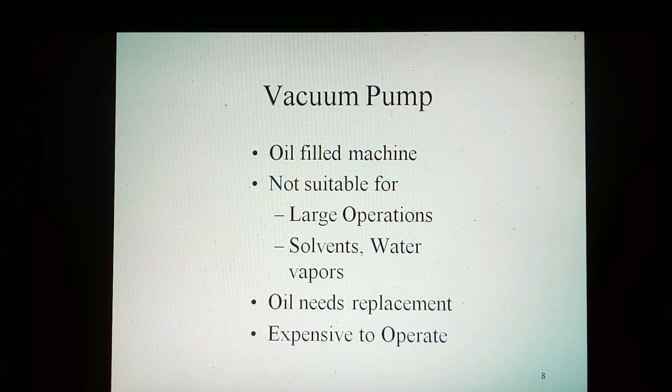Vacuum pump. These are available in single and double stage and are oil-filled, rotary vane-type positive displacement pumps where not only the complete assembly is immersed in oil, but the shaft seal is also designed in such a way that it totally eliminates the possibility of suction of air through it. These are designed to achieve maximum vacuum in a very short time, and the rise in temperature of the unit also remains under check, which in turn reduces the wear and tear of its components and makes it suitable for noiseless and trouble-free performance for years, and thus helps in reduction of repair bills.